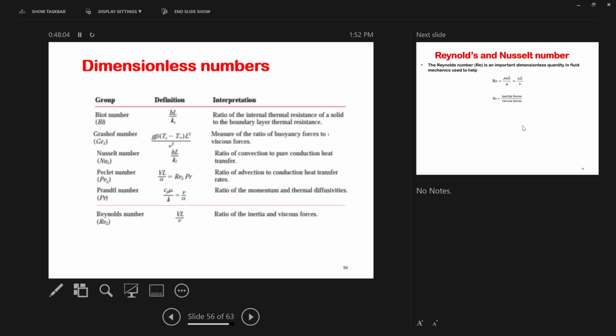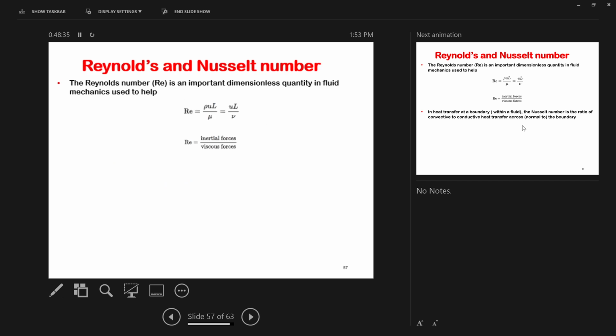The Prandtl number is essentially a measure of the dominance of momentum diffusion versus thermal diffusion. So which one diffuses faster, the momentum or the energy of the system? But in our case, we are only dealing with air, so the Prandtl number in our case is going to be 0.71. That's all you need to know at this point, as far as it comes to the Prandtl number. So let's talk a little bit more about this equation.